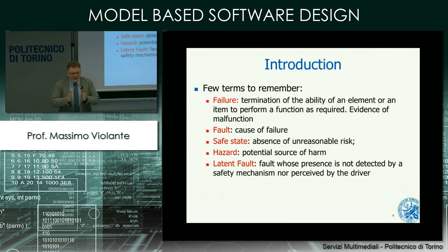So the issue we want to deal with is the failure. We know that something is going to stop working properly in our item, and so we have to be able to cope with that. The first thing that we have to recognize is that the malfunctioning will result in a failure. This means that our item will terminate the ability to deliver the expected service. The failure is provoked by a fault. So the physical component that gets broken due to aging, due to incorrect assembly, due to an accident